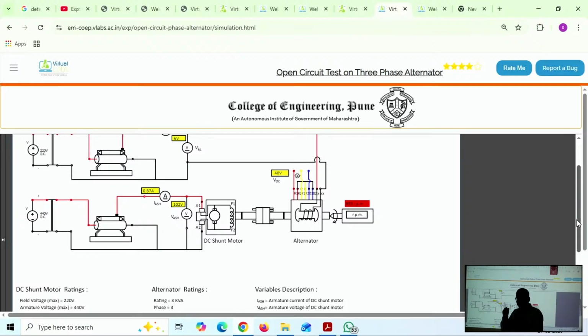So to follow that practice, we start from zero voltage and gradually vary it by means of a rheostat, the safest method. In practice we are controlling the armature, because to avoid high currents at the start, we always start from zero, slowly. If we suddenly take it from higher, the starter may get sparks.